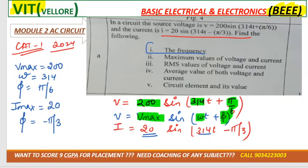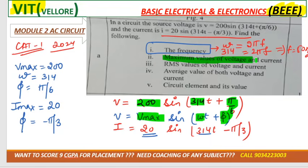Now let's see what they have asked. They asked you to calculate the frequency. We know omega is equal to 2 pi f. Omega is 314, so 314 is equal to 2 pi f. So f is 314 divided by 2 pi, right? Pi is 3.14, so you will get the frequency as 50 hertz, right? In the next part they have asked the maximum value of voltage and current, which we already calculated by comparing the equation. Vmax is 200, Imax is 20, right?